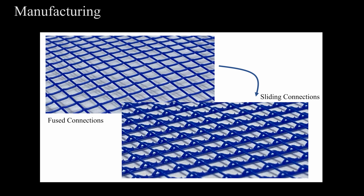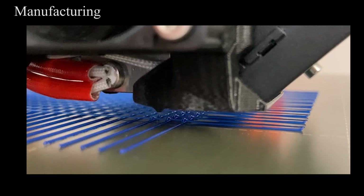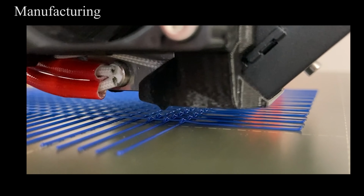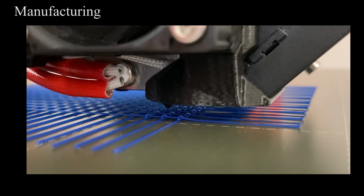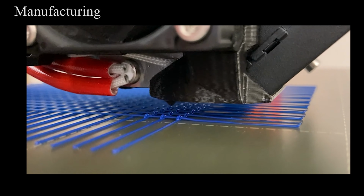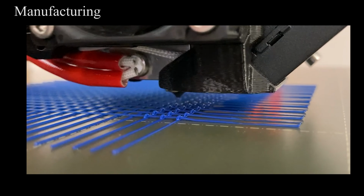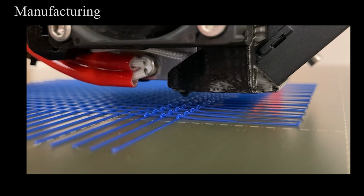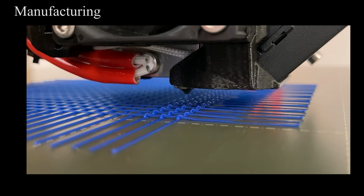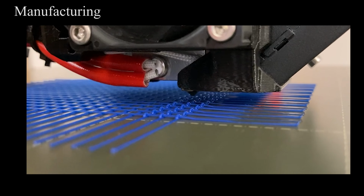To create sliding connections in practice, we proceed in 3 steps. We first print one of the crossing strands in the usual way, by following a planar path. The second strand is printed by lifting the print head slightly before crossing the bottom layer strand. Using appropriate settings for velocity, extrusion rate, and nozzle temperature, this motion leads to well-separated strands. Please refer to the paper for details. Finally, we print an arc-shaped channel that is fused to the bottom layer strand, enclosing the crossing strand without connecting to it.